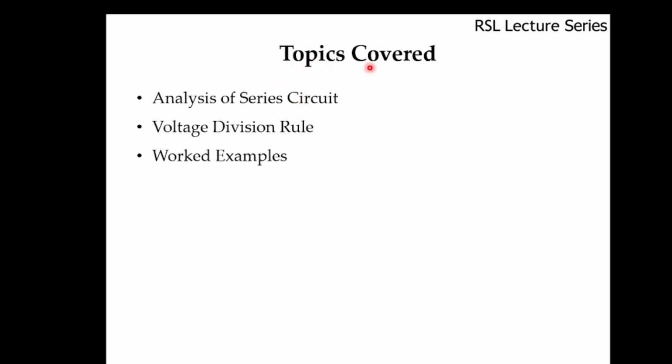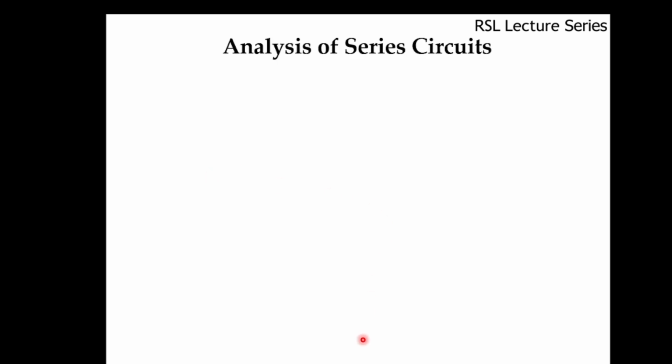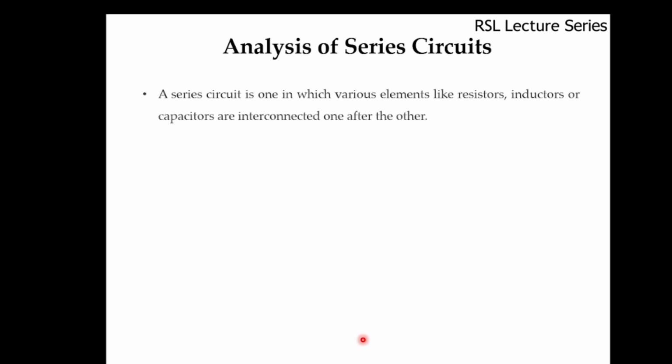In this video, we'll discuss the analysis of series circuits, the voltage division rule, and some worked examples. So first, we'll discuss the series circuit. A series circuit is one in which various elements like resistors, inductors, or capacitors are interconnected one after the other.